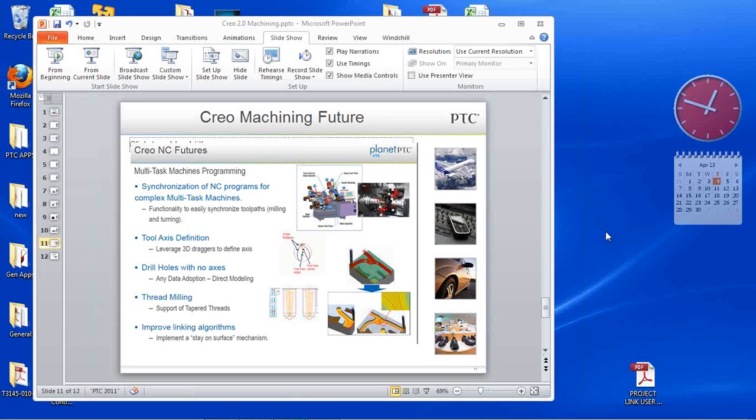If you're creating some type of complicated voluming sequence that you're using a ball end mill on, fundamentally the software for what that feature is trying to do cannot produce all of the essentially leftover material, right? It just can't do that. So if you're doing simple facing material removal features, then yeah, it works well. But if you're doing something a little bit more complicated, all of your leftover material is not going to be generated by that feature. It would be very hard on the software to try to put in all the scallops that were left over. So it's an interesting concept.